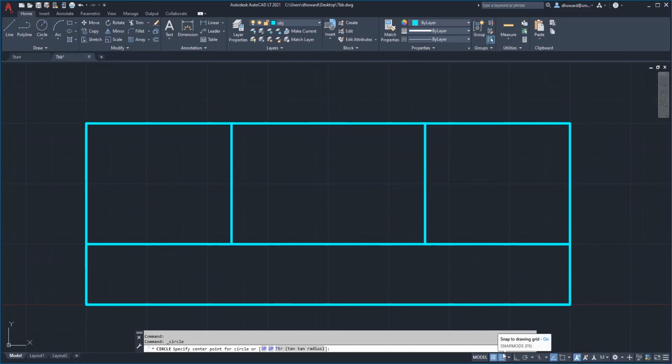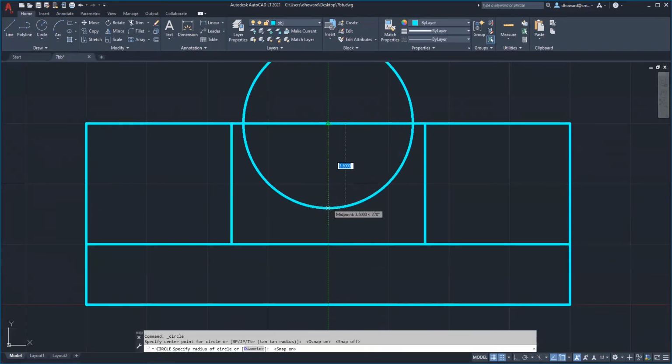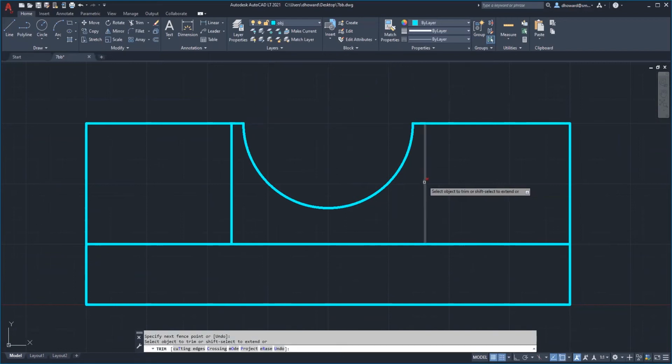But you can also turn on your object snap and grab the midpoint of this line, which is what I'm doing right now. So I grab the midpoint so I'm for sure in its center. And that's a good thing to do. So I use the object snap and I grab the midpoint. And now I'm dragging out to one of the squares, and I think that's the one I'm going to go with right there. So that is leaving a single square width in between. And now I'm going to trim that stuff out. So TR, enter, and just trim those away like that.